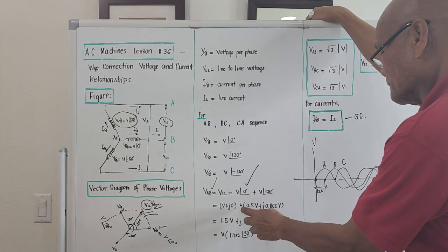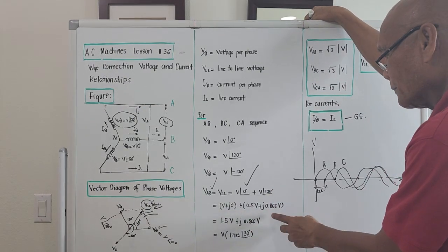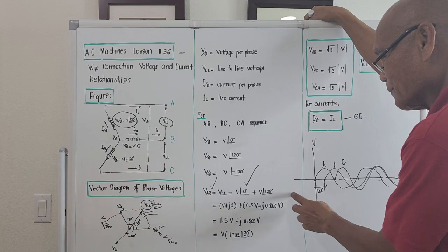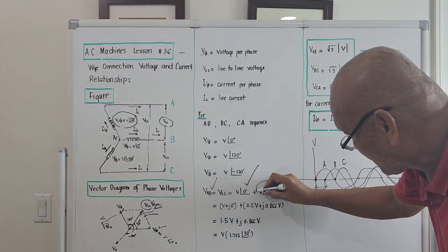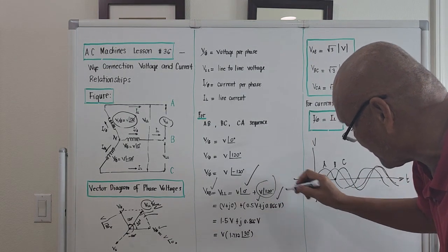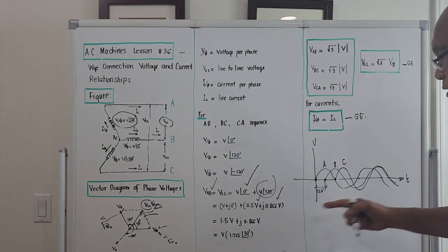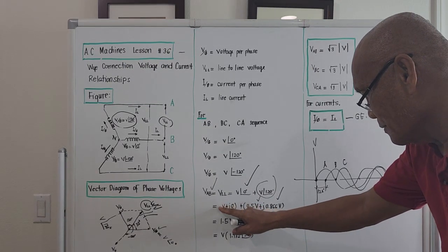Yeah, this is plus. Okay? For the imaginary part, the sine of 120 will be 0.866. This is multiplied by B. Okay? So, the rectangular equivalent of this one will be 0.5B plus j0.866B. Right? Then we try to combine similar terms. Actually, we could remove the parentheses now.